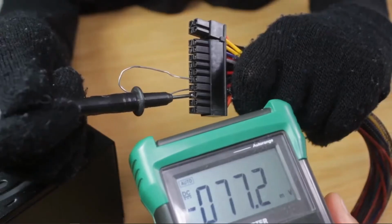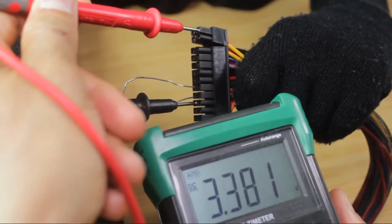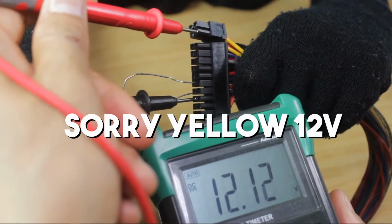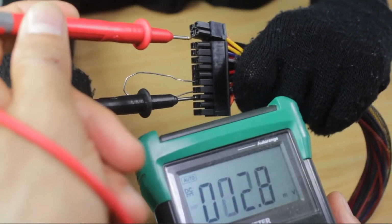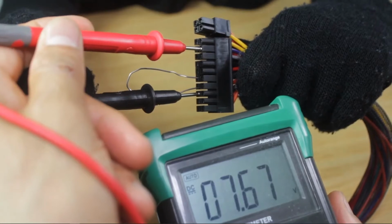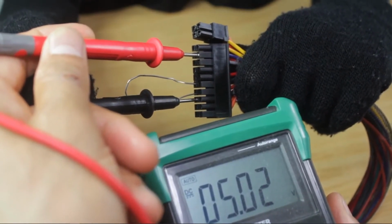Right, we are testing from the top. Should be 3.3 volt orange, so we've got 3.381, perfect. Next is the yellow, it should be 12, 12.12, that's perfect. Next, under the yellow should be 12 something, yep, 12.13. The purple should be positive 5, yep, positive 5.